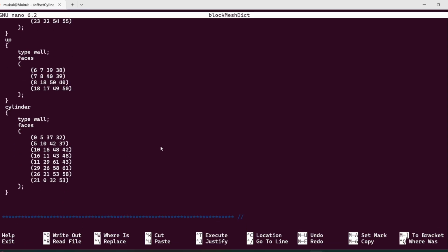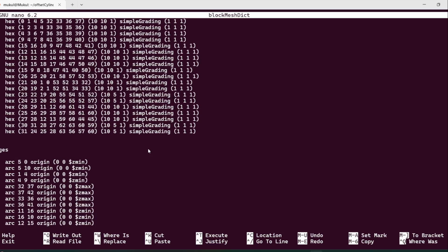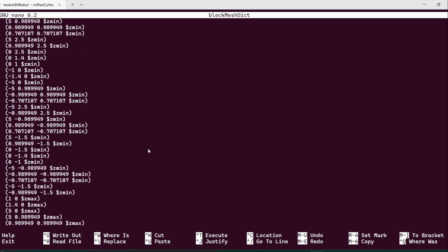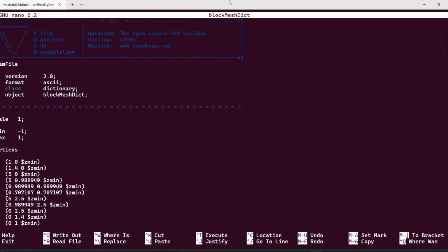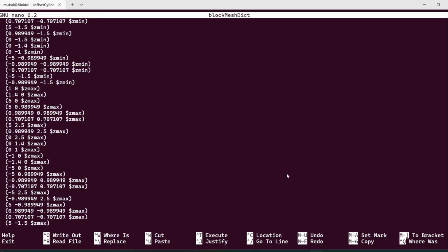Okay, my aim in choosing this case as an advanced tutorial is to demonstrate this type of blockMesh file, because there are many types of blockMesh file. Another way would be to define a rectangular domain with the general blockMesh which we are using, then with the help of snappyHexMesh, put on a cylindrical hole. Then you just run the flow and check how the pattern is moving.